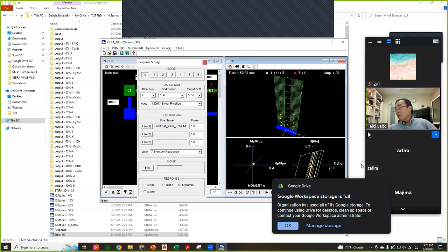Force must be common for two elements. But the capacity is different for viscoelastic. You combine in series, right? Yes. So the force is common for two elements. You understand? So this is viscoelastic, this is metallic. So if you apply F force, this force is also F because of the series. This is also F.